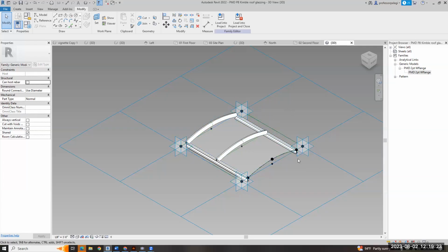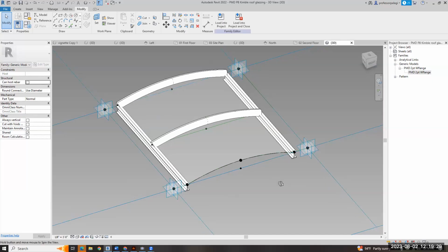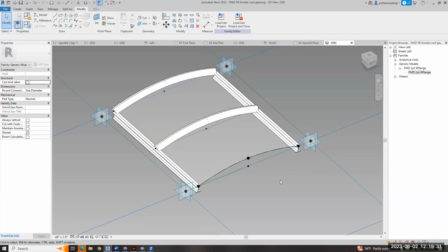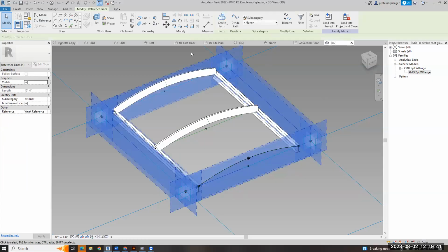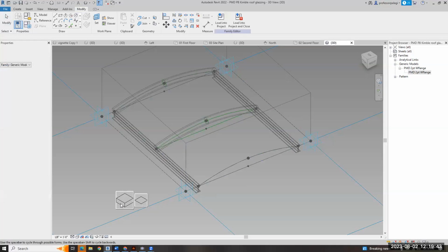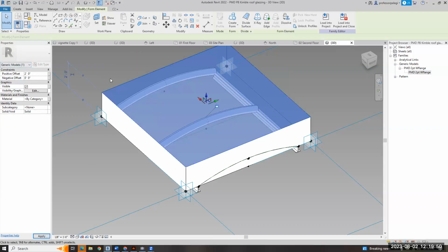Now, remember, we also wanted that other thing above too, right? And so this is where we could come in and that other thing floats above, right? So here's a little trick. I can grab that whole thing and just say, create object, make it a box. And let's say I want that whole thing to be 2 feet above, okay?